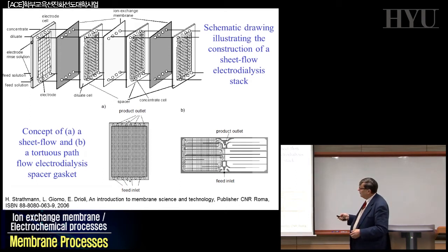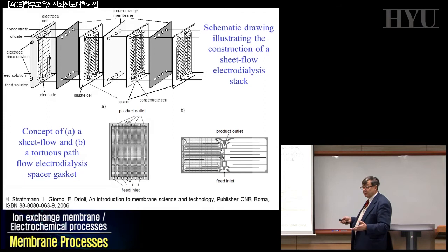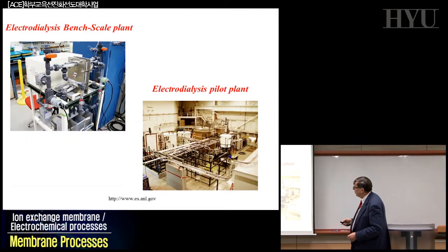So it's quite important how to realize a situation in which the efficiency is maximal, meaning the concentration at the interface is equal to the concentration in the bulk, with no additional resistance, no concentration phenomena, no boundary layer. That is basically related to the design of your spacers. It is a system in which you can induce turbulence, so you can increase the efficiency without spending too much energy. So this is an important part of the story to be considered. When you can do this, at the end, you have a huge plant.